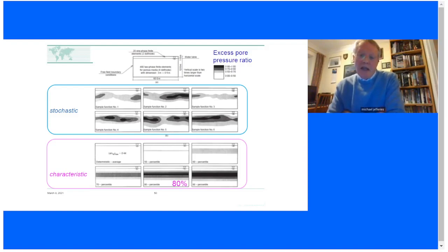removed. The next one across is where we use a 50 percentile or a median void ratio. The top right one is where 60% of the void ratios are denser than what we've used in the simulation. And the bottom left is 70% denser, 80% denser, and then 90% denser. So we're looking at the distribution and saying we took one value from that distribution, what would be representative?